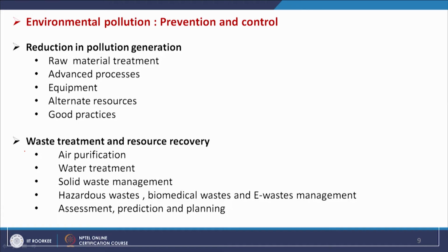Like, for example, one is your conventional combustion and another is your oxy-fuel combustion. In oxy-fuel combustion we will be using oxygen in place of air. So, the carbonaceous material will be producing flue gas which will be rich in carbon dioxide. So, separation of carbon dioxide and its sequestration will be very easy.